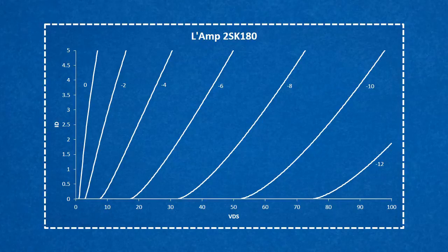It all starts with the characteristic curves for the gain device. You're probably familiar with these already, and you'll recall they're made by measuring the drain current while sweeping the drain voltage, holding the gate to source voltage constant. The curves for your load line diagram must cover the range of voltage and current where the amplifier will operate.